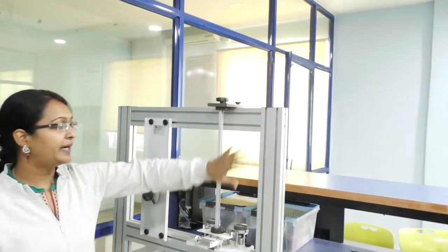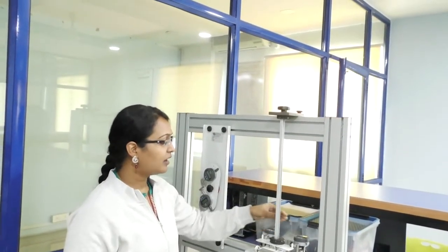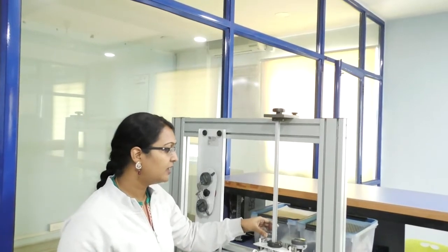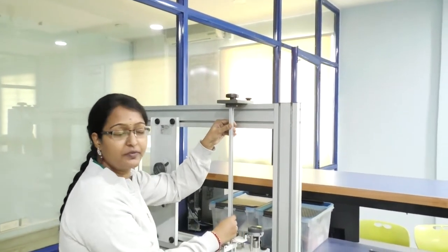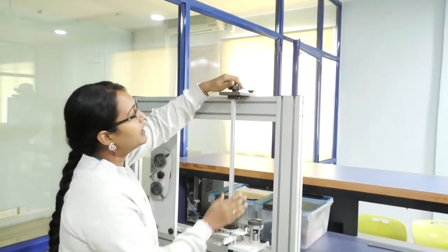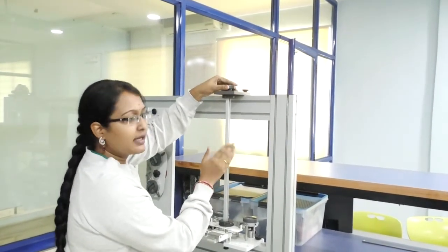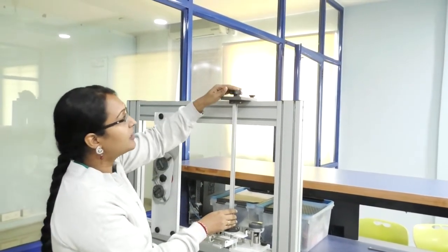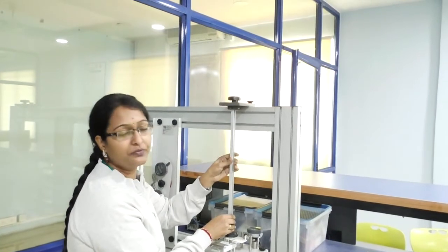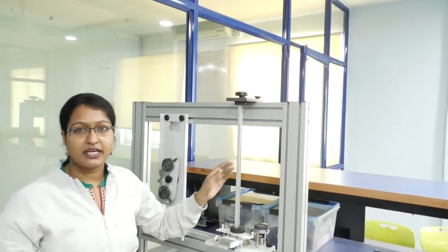This is called the unsymmetrical bending structural unit, and we also have digital indicators for determining the deflections, and we have a closed section B. This is the setup that we are going to fix. This is how we loosen and change the section, and this experiment is also conducted the other way, using an open section. Here we have fixed a closed section B, and for this we are going to find the pure bending, that is, the shear center.